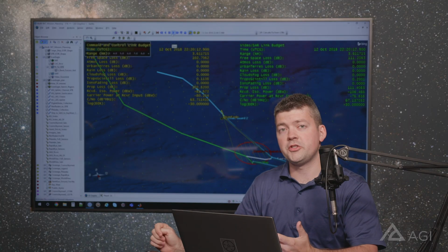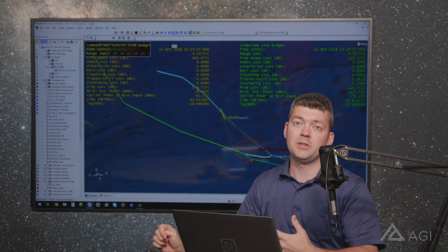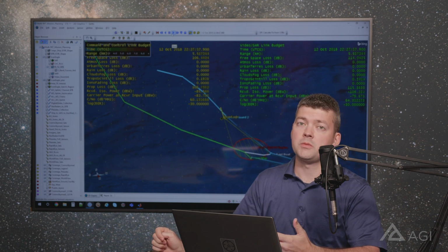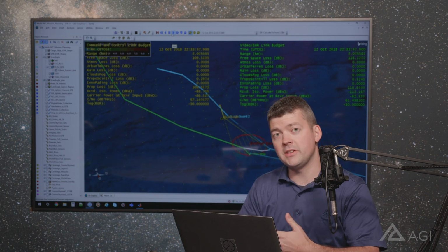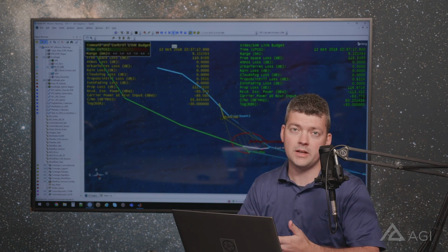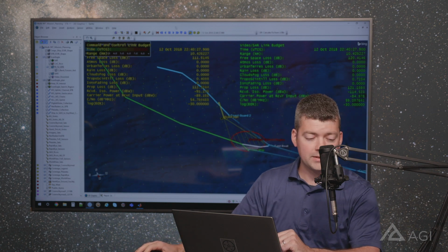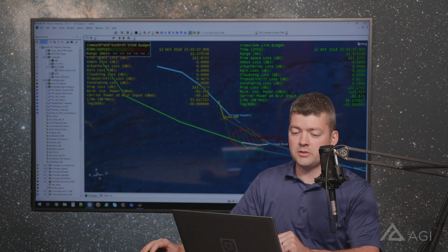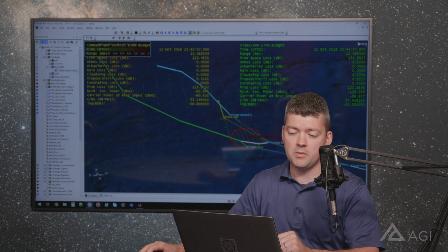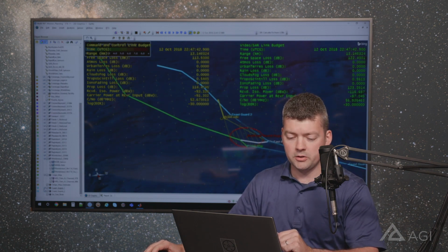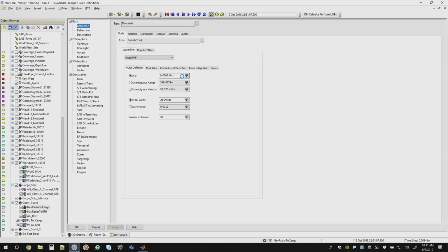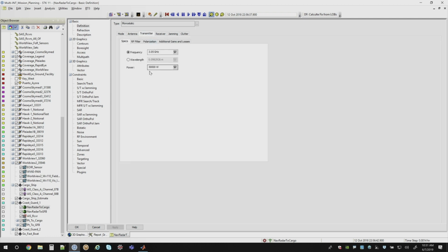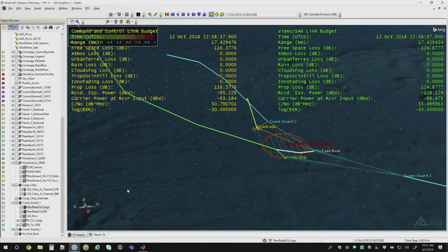Okay, so as the two Coast Guard ships are approaching, they also have their own navigation radars, and so the other thing we can model is the performance of these radars out at sea, and say when might they be able to detect something with a large RCS like the cargo ship and something with a very small RCS like the fast boat, and figure out when that's actually going to happen. So to do that, just like we modeled the transmitter on the comm side, we can also model the search track radars on the ships with similar performance parameters. So we've got PRF, pulse width, modulation, probability of detection, transmit frequency and power, etc. Whatever is appropriate for this ship.